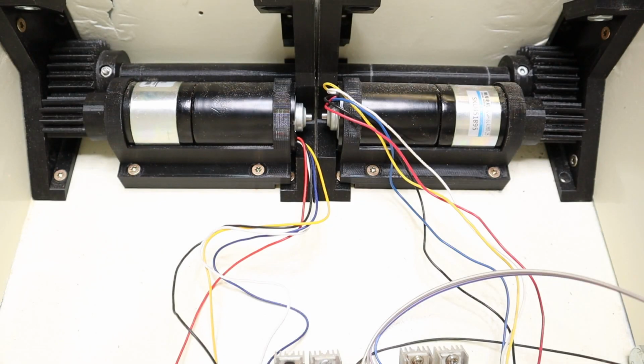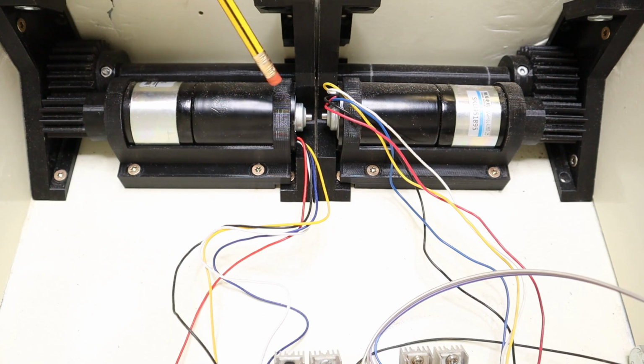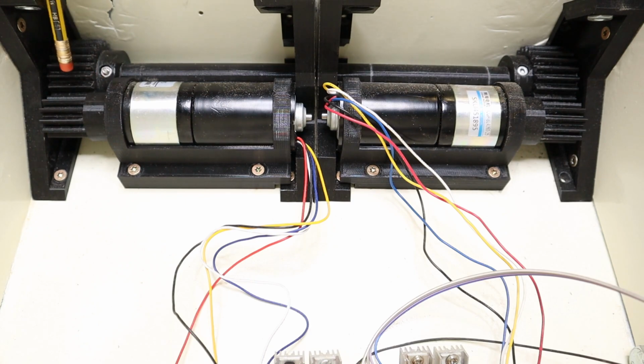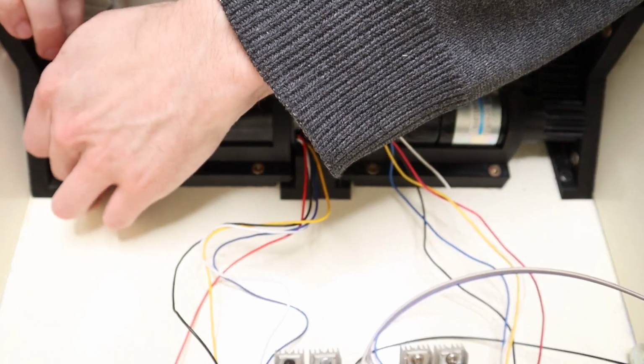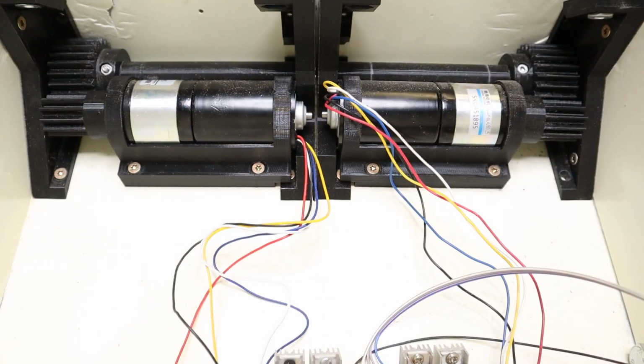You're now looking at the inside of my Wi-Fi tank looking forward. And over here you can see the two drive units that drive the shafts on the left and right side, which eventually turn the tracks. And the problem with these is that the mounting of the motors especially is insufficiently rigid. And because these are 25-degree pressure angle gears, when they are turning and when the transmitted torque is maximum, there is a lot of force driving these two apart.